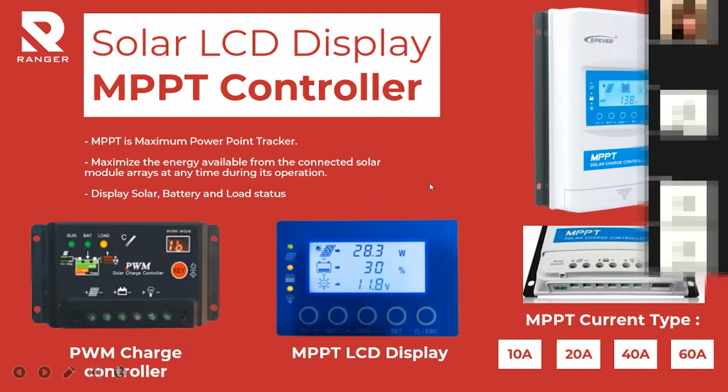This MPPT also supports lead acid and lithium ion batteries. This picture shows the connection, so you can see here plus and minus for solar. From the solar panel it connects to here, from the battery plus and minus it connects to here, and the load here will be the output, for example 12 volt output. For MPPT current, we have 4 types: 10 ampere, 20 ampere, 40 ampere, and 60 ampere. Later, in the formula, I will show you how to choose this MPPT current.